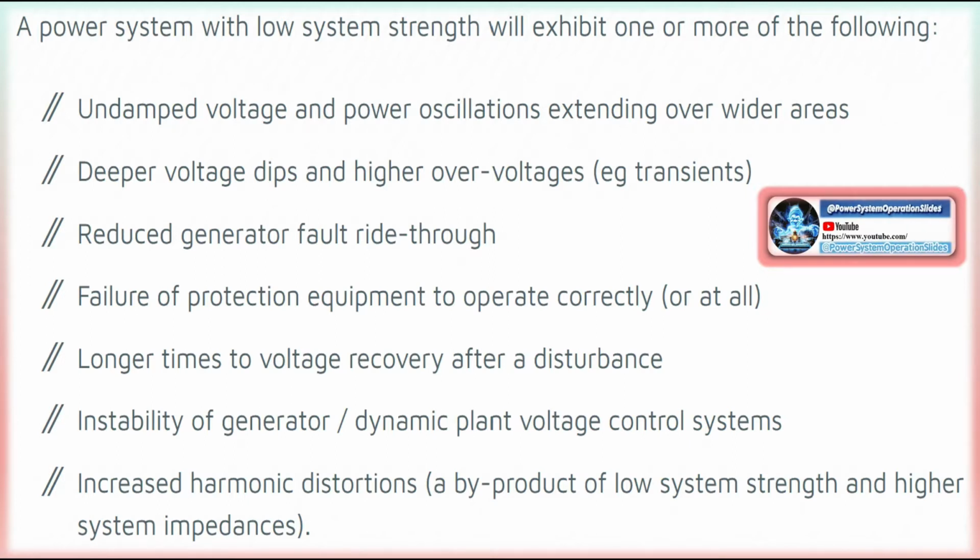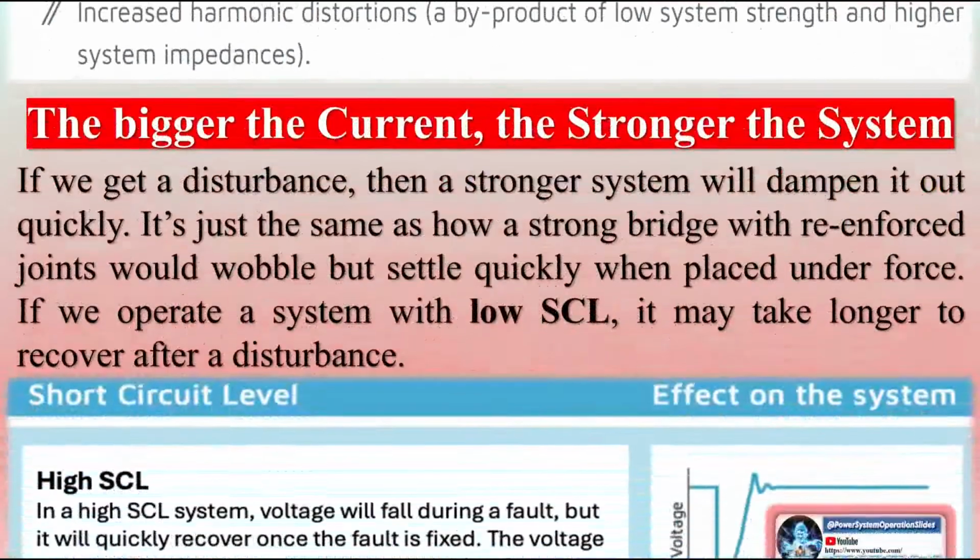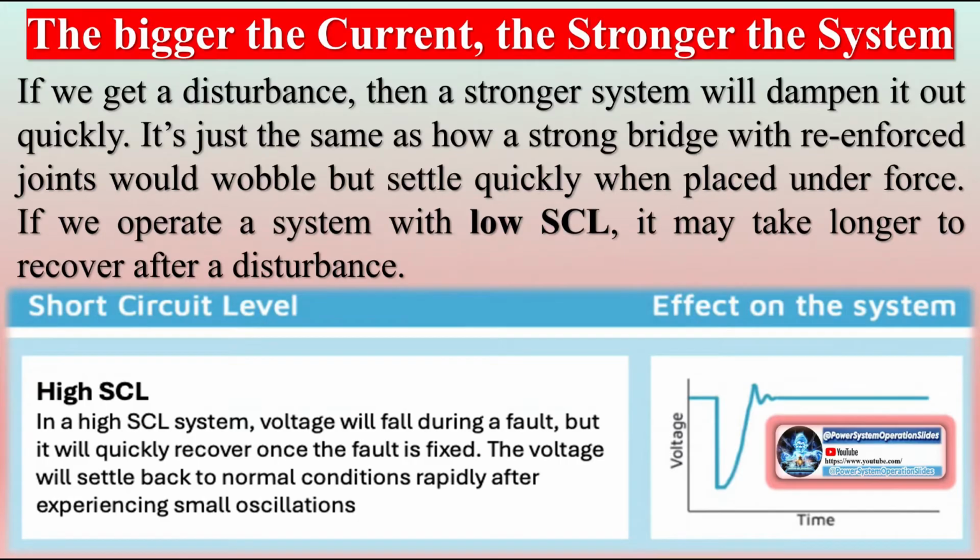A short circuit current can be very large. If unusually high currents exceed the capability of protective devices, fuses, circuit breakers, etc., it can result in large, rapid releases of energy in the form of heat, intense magnetic fields, and even potentially as explosions known as an arc blast. The heat can damage or destroy wiring, insulation, and electrical components. An arc blast produces a shock wave that may carry vaporized or molten metal, and can be fatal to unprotected people who are close by.